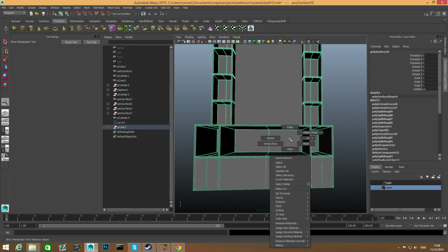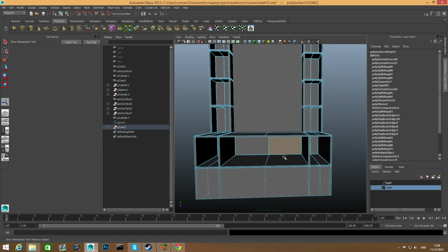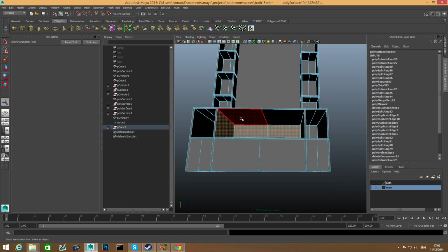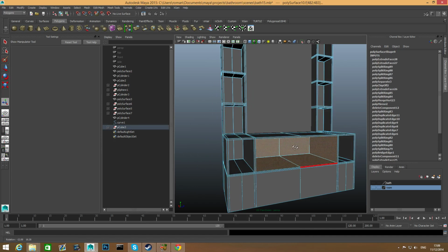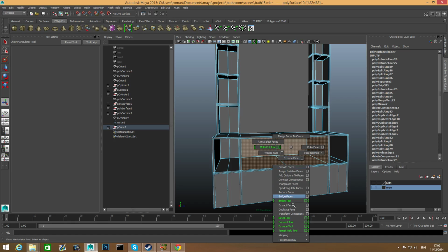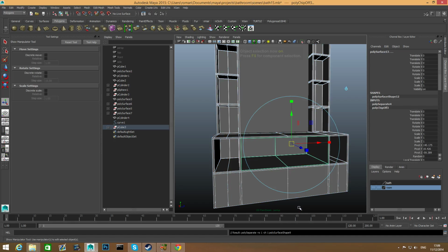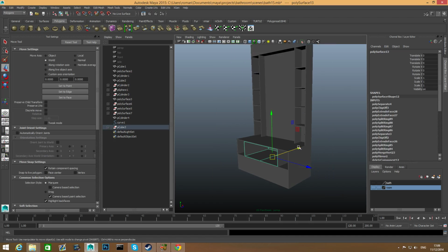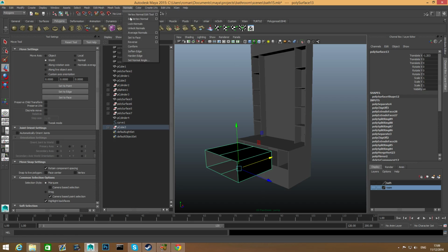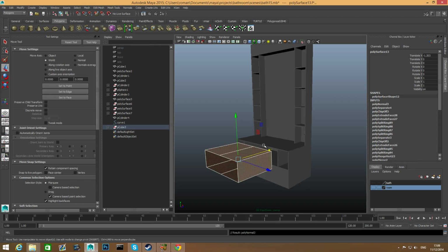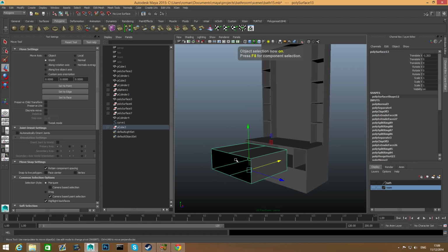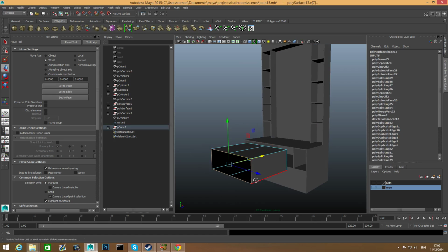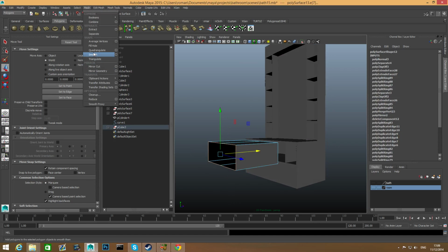So with that done, I can grab this one, and I can shift right click, duplicate face, press F8 three times, Control to unselect the entire structure of this, and bring this outside. Now, in this particular case, what I will do is, first of all, go over and choose reverse normals, press F8, and right click, choose edge, double click on this edge, mesh, fill hole.